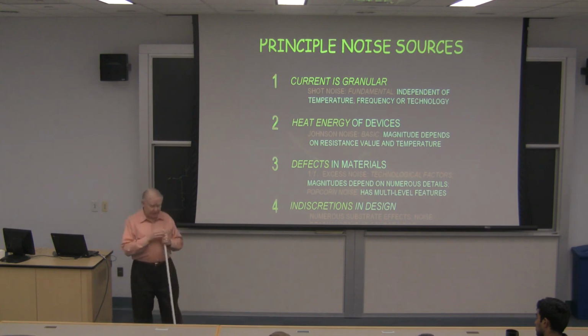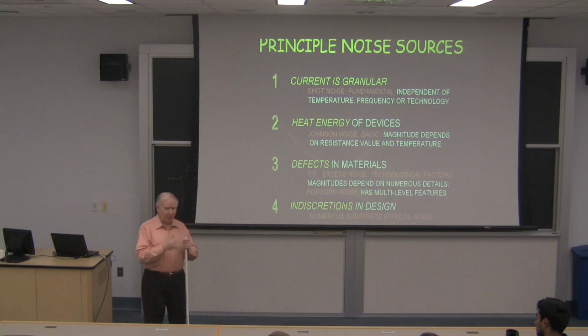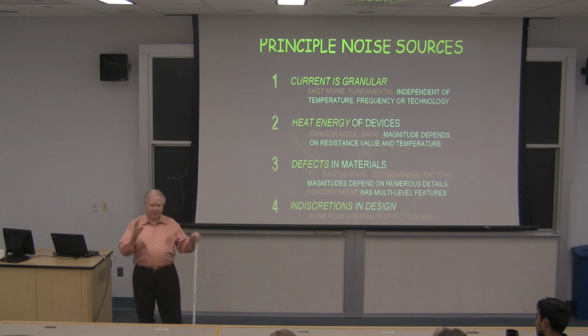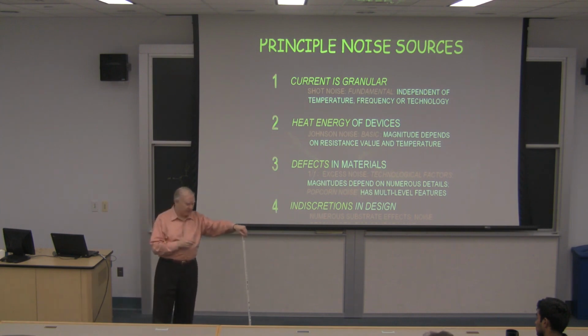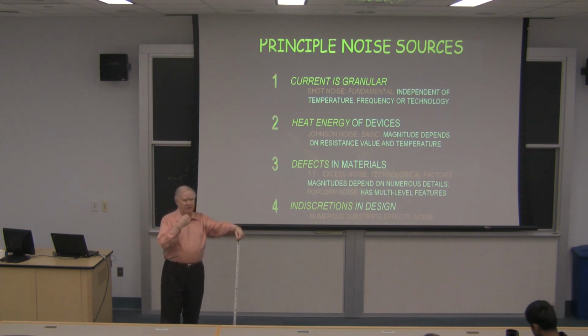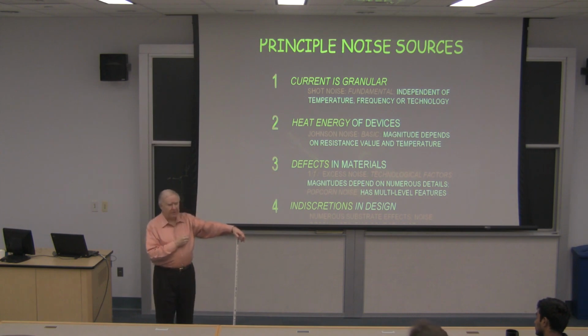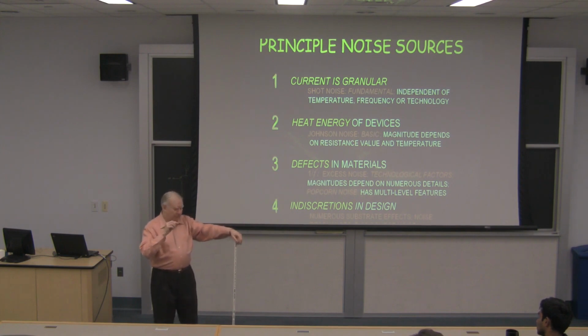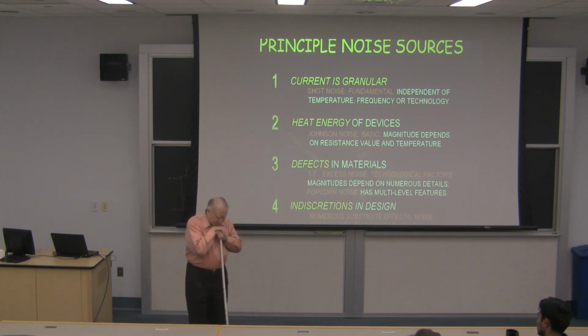When you're designing a little bias cell, you have to treat it as if it thought it was an oscillator, or something very close. And so look at noise versus frequency. It's something you can do with any SPICE-like simulator. Look at noise versus frequency, and it's not uncommon to find some very sharp noise resonances where the noise is 10 or even more times the noise at, say, the mid-band. And the first thing you do when that happens is you drop everything else you're doing and you attend to that. I have a little philosophical point to make here, and we'll never get through all this, but that's okay.